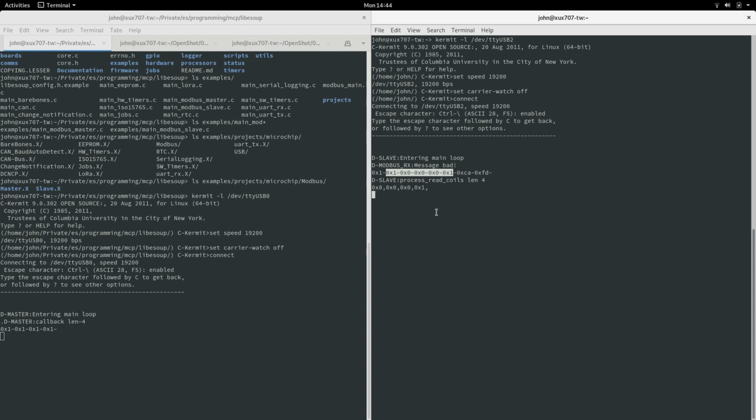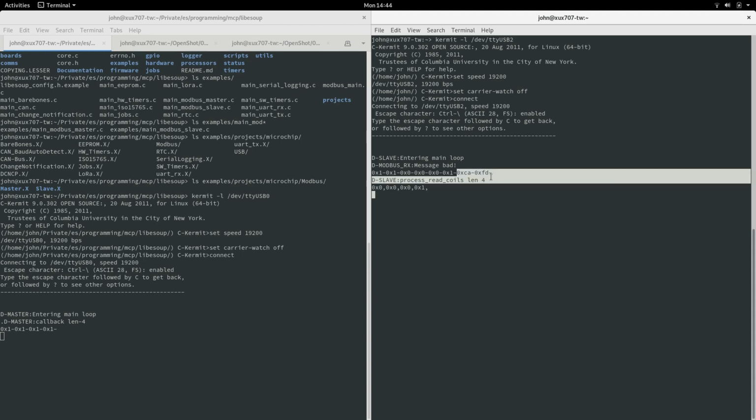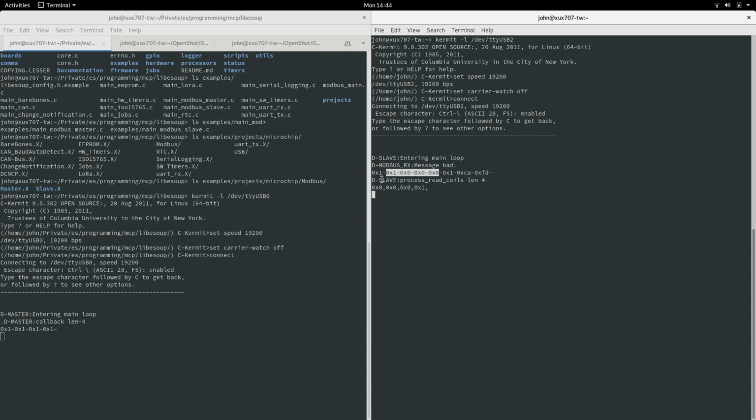When that frame is sent down to layer 2, which is the data link layer, it adds on our target address. And layer 2 also adds on a CRC on the end. So the master sends those bytes to address 1 down to layer 2.